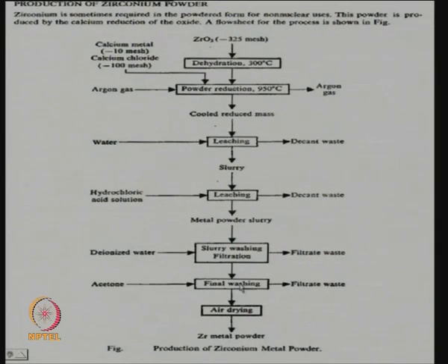So, all these are examples of metallothermic reduction, here sometimes by magnesium in gas phase, sometimes by calcium in gas phase. We are adding calcium chloride to drive the reaction to the right. It's very simple principles of how you manipulate the free energy change for the reaction. If there is not enough heat, you have to supply heat, otherwise things can move on their own.